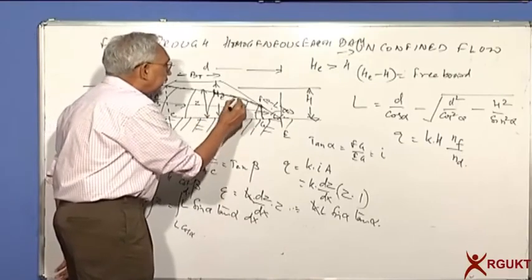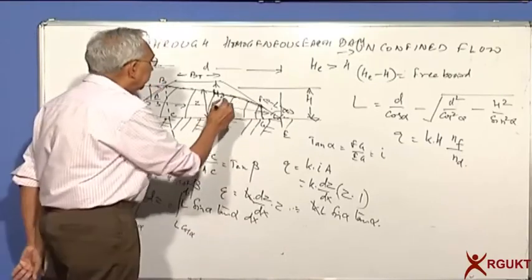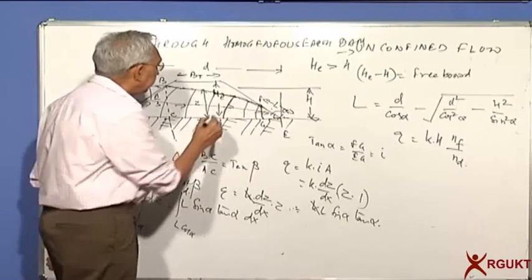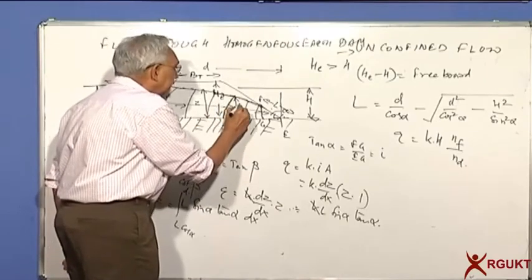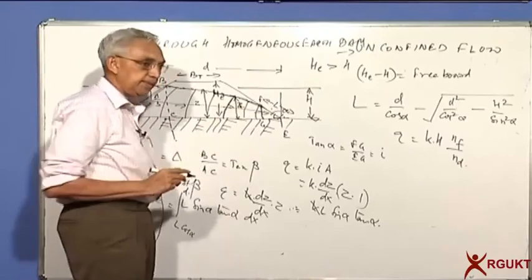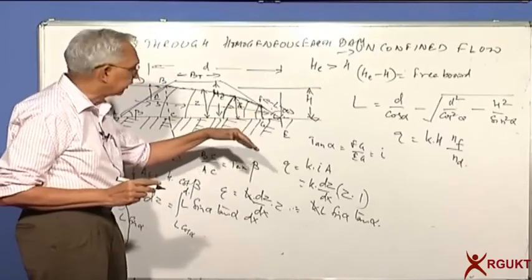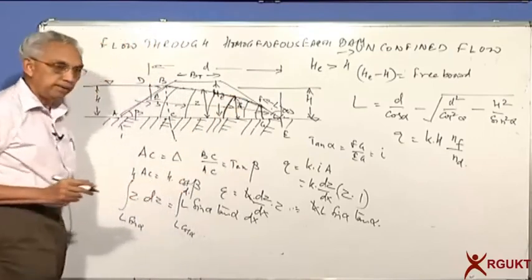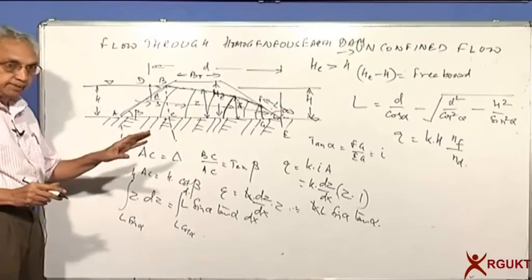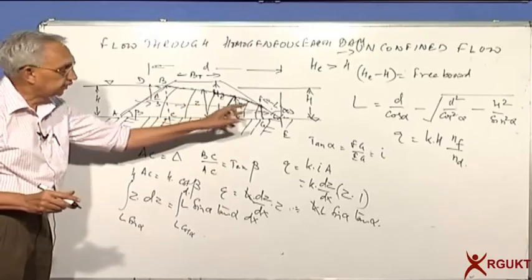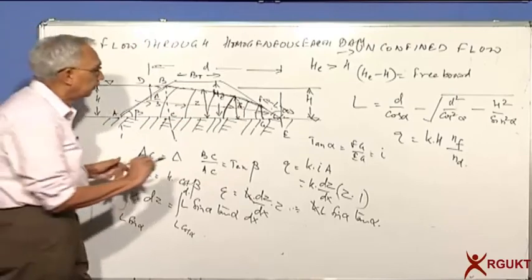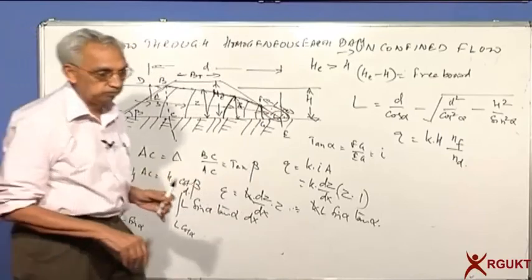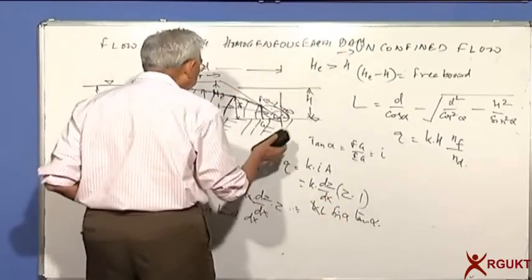Similarly, you can calculate the head drop, because basically this equipotential line is hitting the downstream face at the phreatic surface here. So the potential is equal to simply the elevation at that point, Z. If you know the height of the phreatic surface, the potential corresponds to the top of it. The only point I'd like to mention is we never design an embankment with the phreatic surface touching the downstream face, because once the water comes, this part of the soil becomes very soft and it will start collapsing. So what we try to do is introduce a drain.